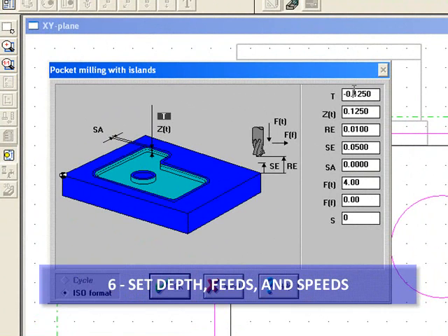All right, here's the deal. My total depth, that's how far I'm going to go down in the piece. You need to set that to a negative value because you're going down into the piece. You're at 0 on the top, you're going down negative, in this case, 0.125, which is 1/8 of an inch. My ZT is the change in depth with each pass. I'm going to make that 0.125. That's an absolute value, obviously. It's positive. That should mean I make this in one pass.